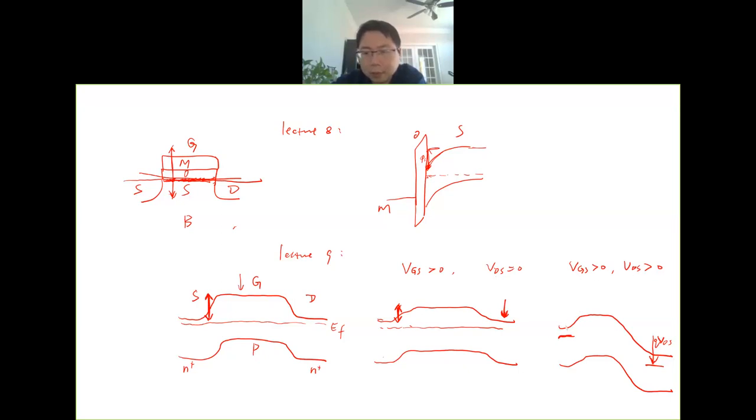You know the electrons are stored in the source. Once you push down the gate and reduce the barrier, the electrons can jump over, then fall down along this hill, and reach the drain. So this is how the current flows in the MOSFET. Any questions on this slide?